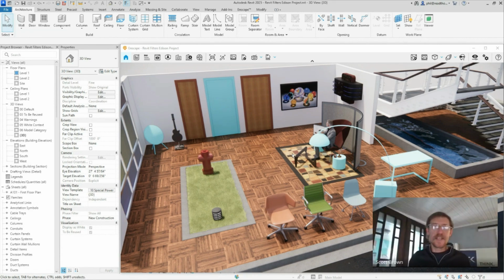Yeah, there's all kinds of things like that, right? If there are certain elements that the owner is going to buy but want us to install, and then there's things that the owner is going to buy and the owner is going to install. But our drawings, we show everything because maybe there needs to be an electrical outlet for something that the owner is providing and installing later after we're gone. So having filters that clearly indicate whatever the responsibility to furnish, the responsibility to rough in, that's the other one, because there may be a third person that's responsible to rough in, and then the person who's responsible to install it, right? So there's kind of 3 choices there.